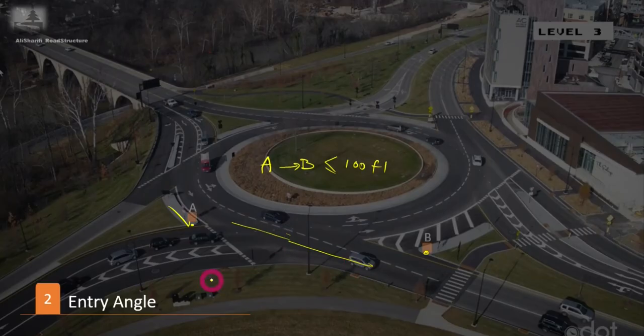for measuring entry angle. In this case, all you need to do is to draw the center line of the entry, then extend it till it intersects with the inscribed circle. Now, from this point here, you draw a line tangential to the center line of entry. You do the same for the exit. Draw the center line of the exit, extend it till it intersects with the inscribed circle, and again draw a line tangential to the center line of exit. Now this angle here, or this one, is twice the entry angle.